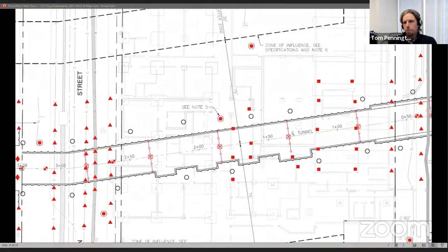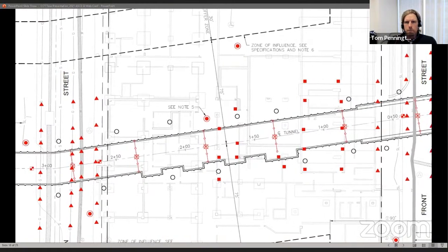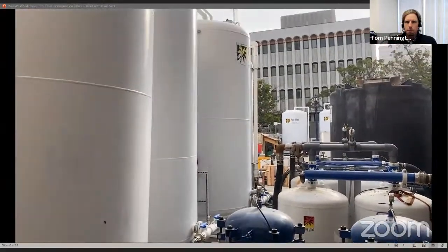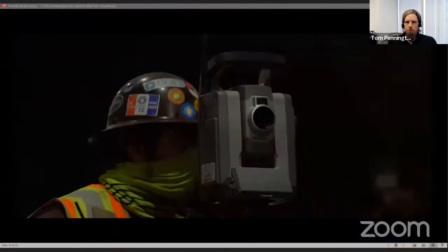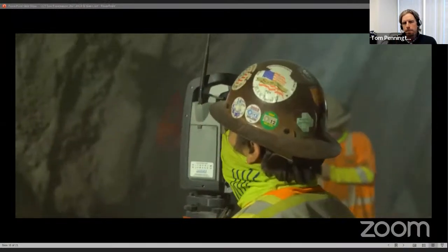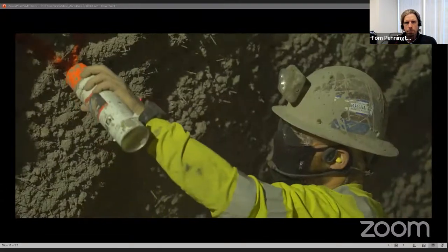Furthermore, liquid level sensors were used on load-bearing columns of buildings. Piezometers measured the depth of groundwater that was lowered by the dewatering wells, and manual convergence monitoring of prism arrays set inside the tunnel was performed with each advance of the tunnel heading to ensure that movements of the tunnel support system are within estimated displacements.